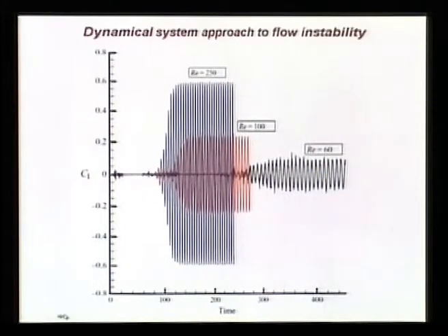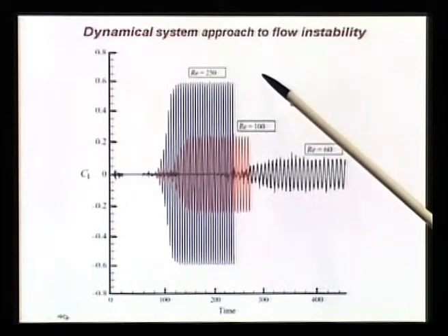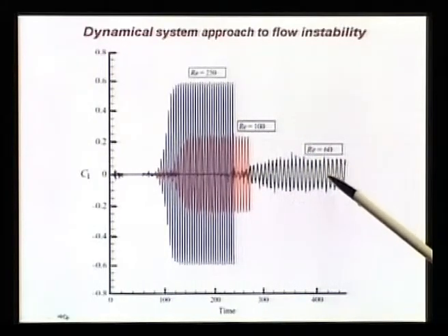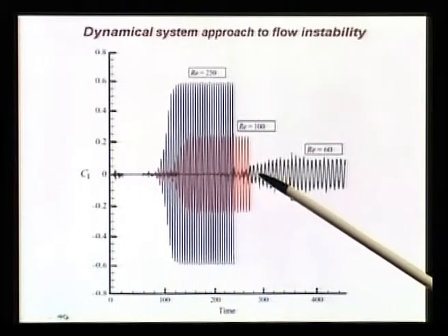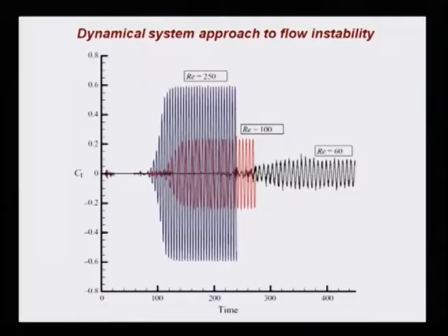The other thing that you also notice is that there are certain interesting features. For example, this saturation amplitude variation with time is very minimal for higher Reynolds number, but while you look at R equal to 60, although one would expect from Landau's theory that you would have attained an equilibrium amplitude, it is not so. You can see quite a bit of jagged edges, and it's something specific about this particular lower Reynolds number that is where you see most of this variation.